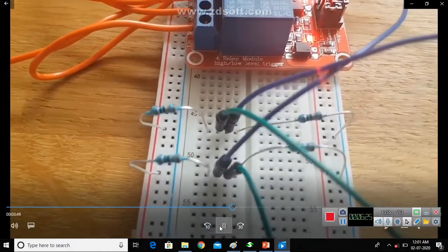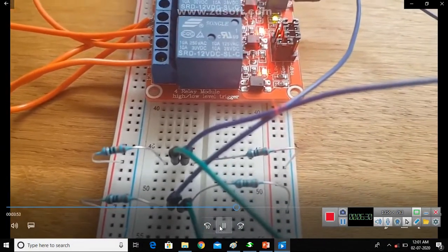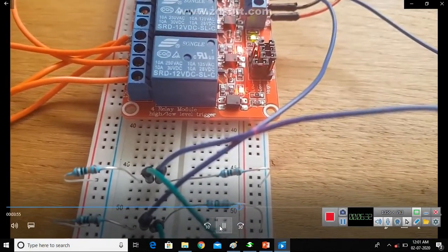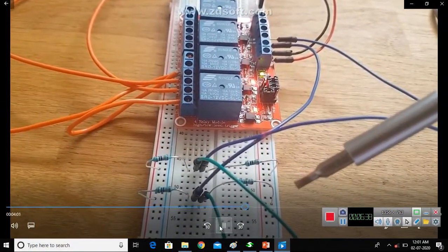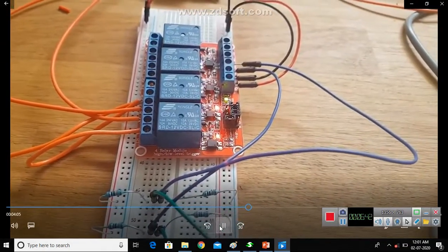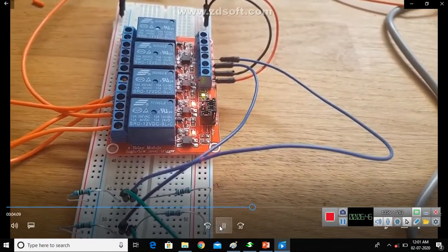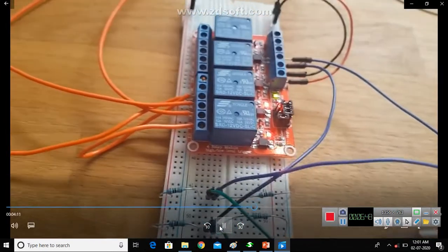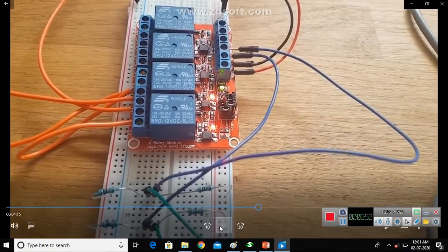So actually these pins would, in an equilibrium situation, just sit around 6 volts, i.e. there's a 100k resistor there, a 100k resistor there, and I've done this so it doesn't really matter if I use a PNP or an NPN proximity sensor. I can just put anything in, really, because the board is sensing a voltage change up or down.